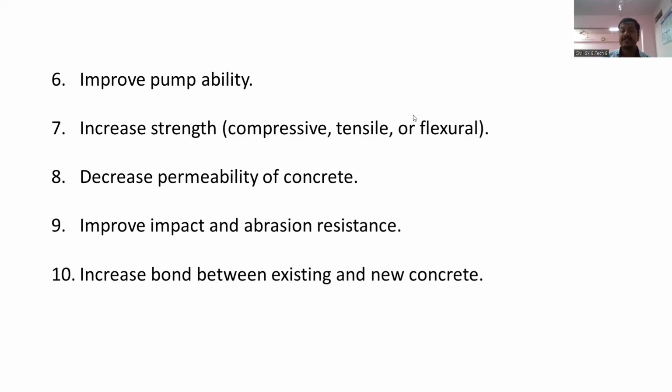As per our Indian standard specification, we can take concrete up to a distance of 2 kilometers in a horizontal direction, and in the vertical direction around 50 meters. We can lift our concrete up to 50 meters through concrete pumps. So to take concrete to a particular height, maybe G+1, G+2, G+3, you use concrete pumps.